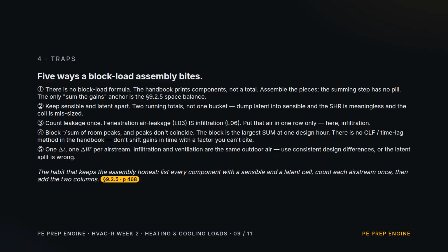Traps. 5 ways this bites. 1. There's no block load formula. Assemble the pieces, the sum has no formula. 2. Keep sensible and latent in separate totals, or the ratio is meaningless and the coil is wrong. 3. Count window and door leakage once, it's the same air as infiltration.